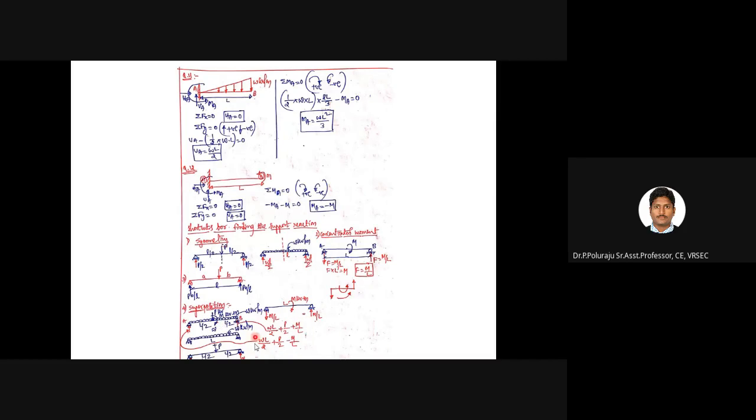And here it can be seen how to convert this different type of loading system into different types of beams. You can see here, this is equivalent to first, a simply supported beam with only UDL, plus one with only point load, and the next one is only with the moment diagram.